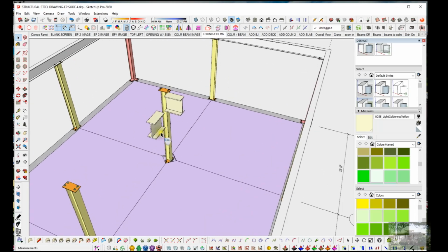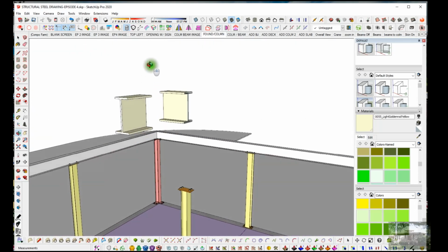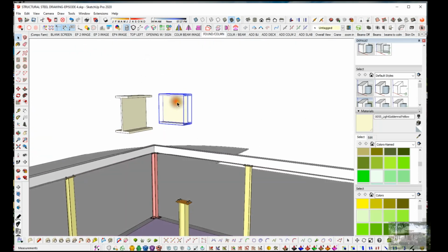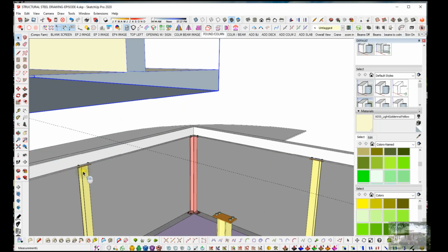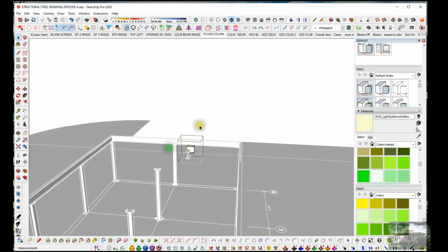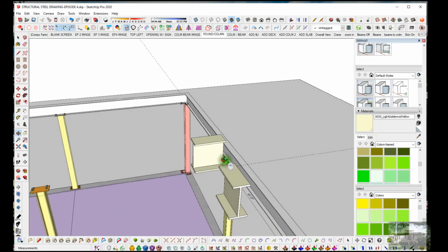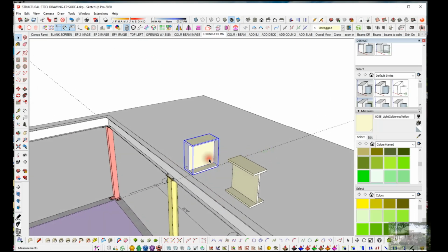Okay. This, I think, if I'm not mistaken, I think this one's the 12-inch, to tell you the truth. Yep. Again, double click, get inside, draw a line to fill it in, click outside of it, so we're on the outside of that group.